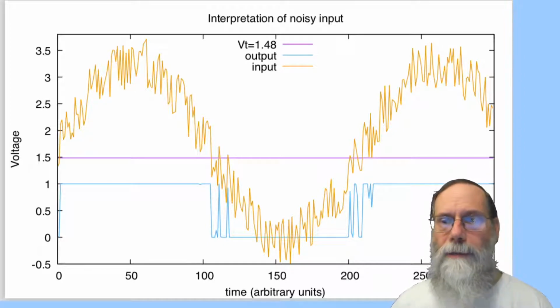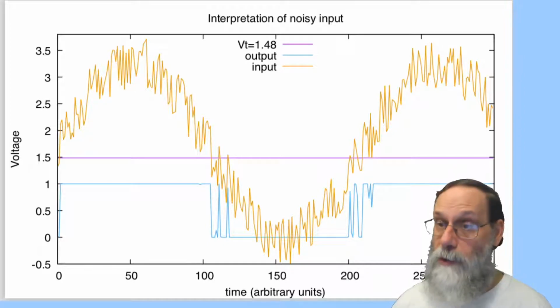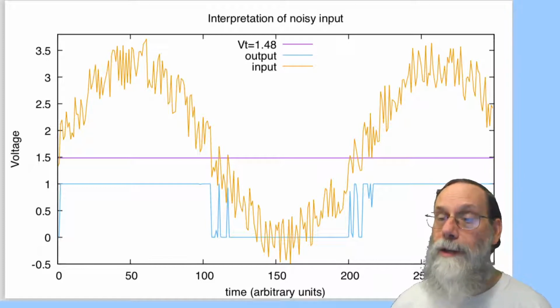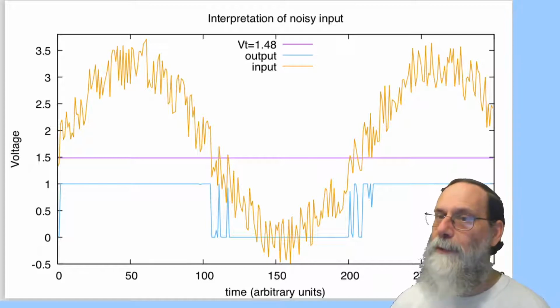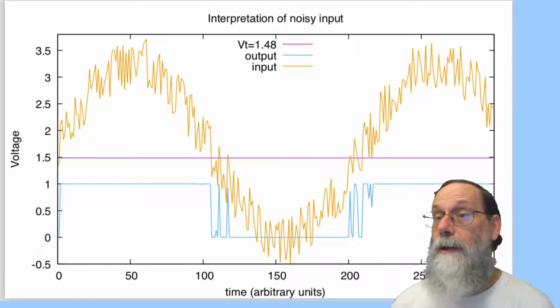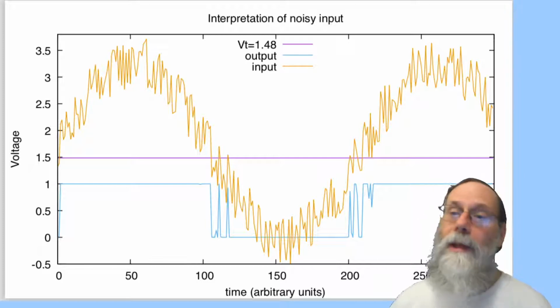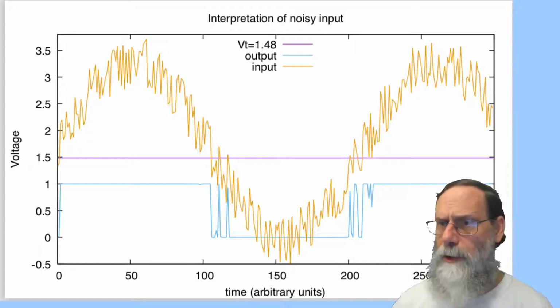Well, a lot of the devices that we want to control with simple on-off controls are ones that don't tolerate this sort of flickering on and off. You're trying to light a flame, you don't want to say, oh, turn the flame on, turn the flame off, turn the flame on, turn the flame off, because you may not be able to manipulate your valves quickly enough to do that. You may end up with all kinds of damage to things because they're not designed to be moved, to change that often or that frequently. So it's not a desirable solution.